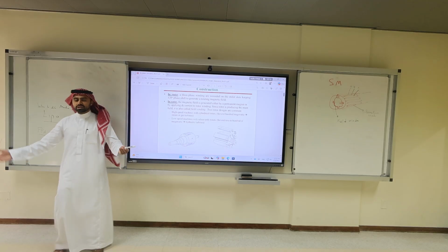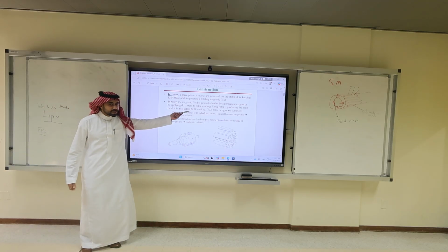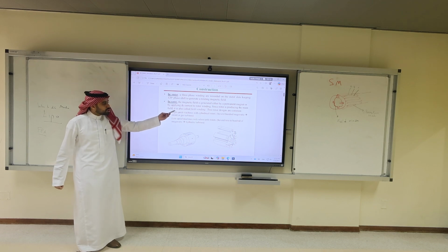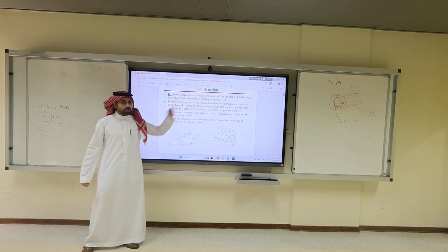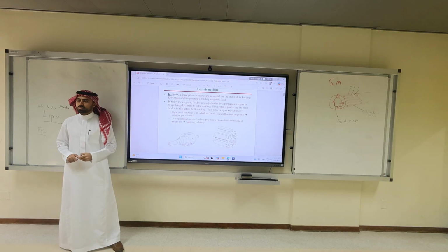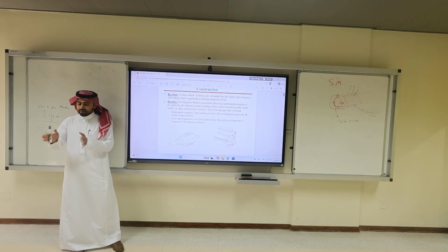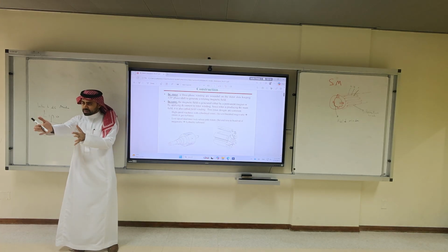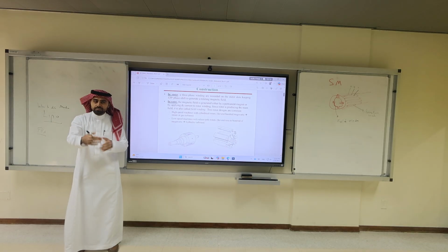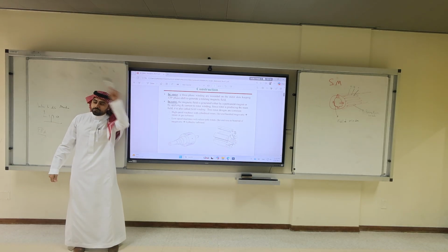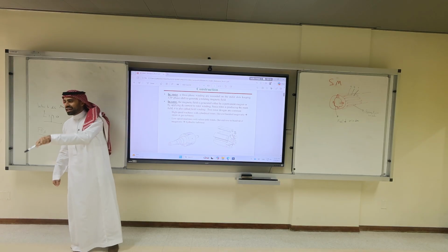This is one of the questions. This is one of my favorite questions in the exam. You have to watch YouTube to remember these questions. Why do we put DC current in the rotor winding? Why? We want a fixed magnetic field. We want a uniform magnet. Uniform. It's not fixed. If the rotor is standstill, it's fixed, constant flux. But because you're spinning it, it becomes a uniform rotating magnetic field.